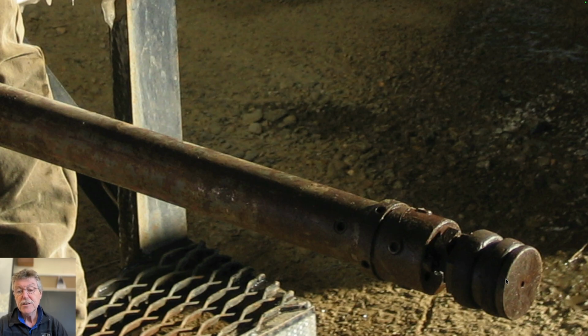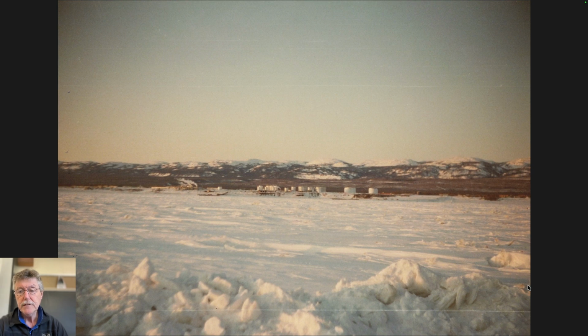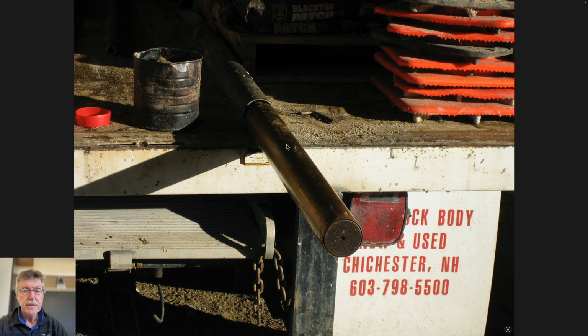You can push this syringe, if you like, down all the way to the end, which is what it's like here. This is the coupling where it attaches on the tube. The piston's advanced all the way in. You put it on the gantry, lower it down the hole, put it on the base of the hole, and then with the weight of the drill rig, you push it the 18 inches or so into the ground. As it goes into the ground, this piston comes up level with the base of the borehole, so there's no air gap between the clay that's kind of advancing inside this, but it's not advancing inside it. It's the actual tube that's going down over it.